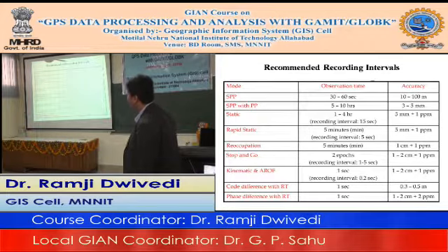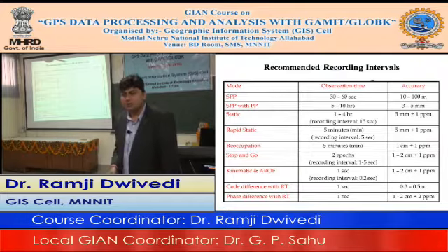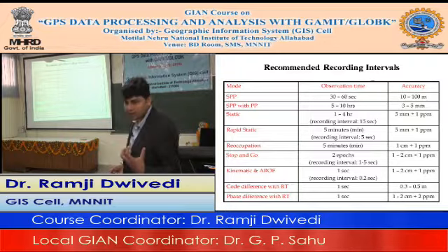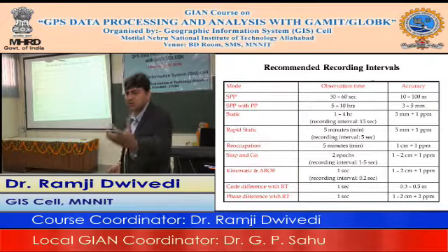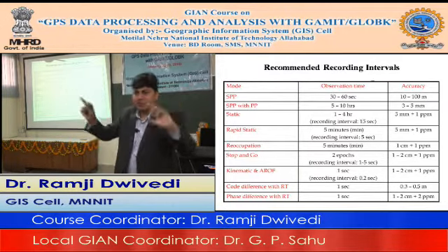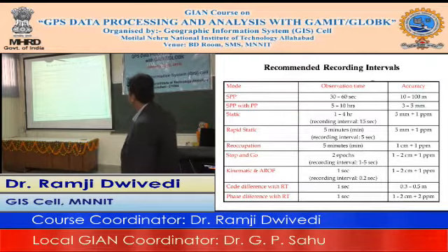So based on these different modes, you choose in your field, and you could deviate from the accuracy requirement also. How much accuracy you require in your observation correlates with how long the session length would be. That also needs common satellite geometry for both rover and receiver.